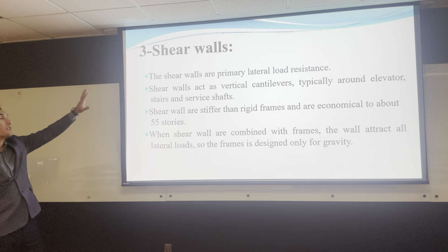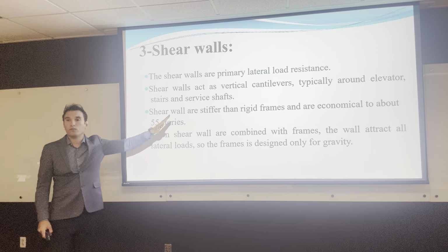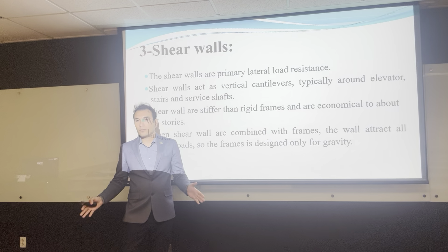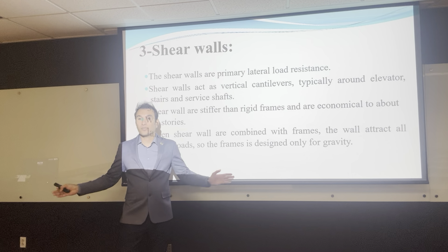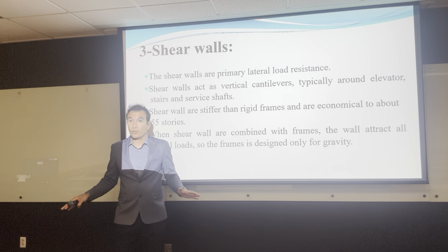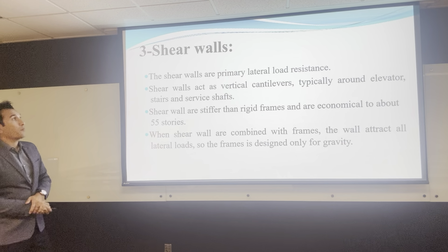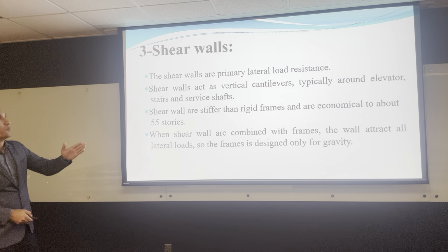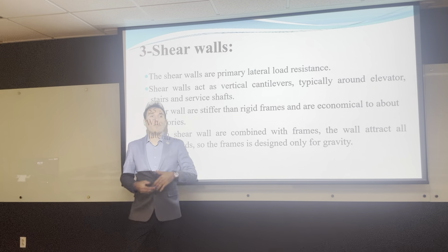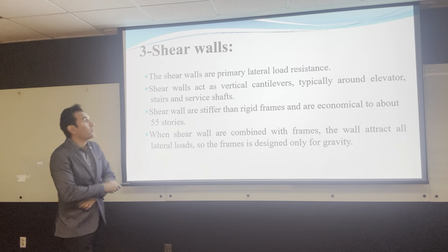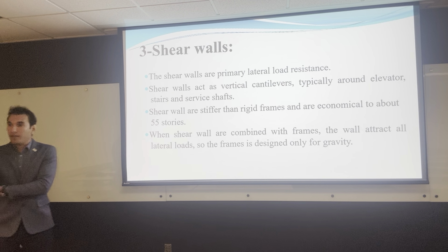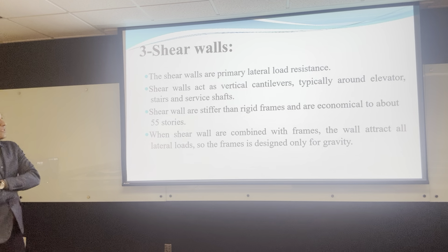And this is the best system ever that you can use to resist lateral loads: shear walls. It's usually used in most of the buildings around the world, like even Burj Khalifa, it's all shear walls. This is the system that can decrease the displacement, that can make the building more rigid, that can absorb the lateral load. Okay, so shear walls are the primary lateral load resistance system. Even if you have frames inside your building, shear walls are taking most of the lateral loads. So shear walls act as vertical cantilevers because they are fixed at the base and then they are free all over the length of the building.